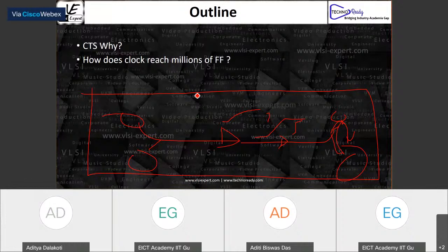Nope. It will not. As long as the clock is symmetric, it doesn't affect the setup, right? Your setup and holds are not dependent on the delay. They are only dependent on making sure that the clock reaches at the same time, or on the relative clock skews.